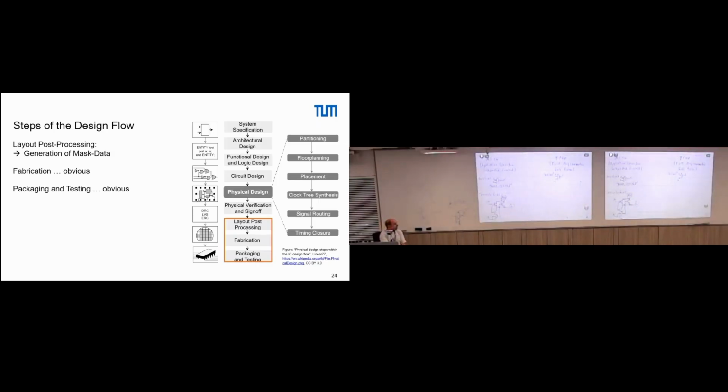Well, what you have on FPGA are so-called lookup tables. So the next level here would be something like a lookup table. More generally, maybe I write this, BEL selection, and BEL stands just for basic element. This is, let's say, Xilinx language. Other FPGA vendors may call this a little bit differently, but they all mean the same. In our case, we use a lookup table, LUT.